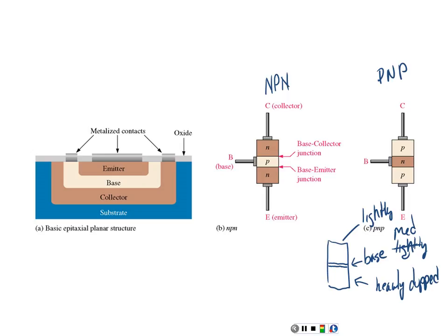If I've got some P material holding in my hand, does it carry a P charge? It's a simple question, guys. Yes or no? No. It doesn't carry a charge at all because your electrons and your protons still match, right? It's just that now we've got a bunch of holes floating around in there that can be moved. And an N material does not have an N charge. It's just that it's got a lot of free electrons in there, but the electrons and the protons still match.